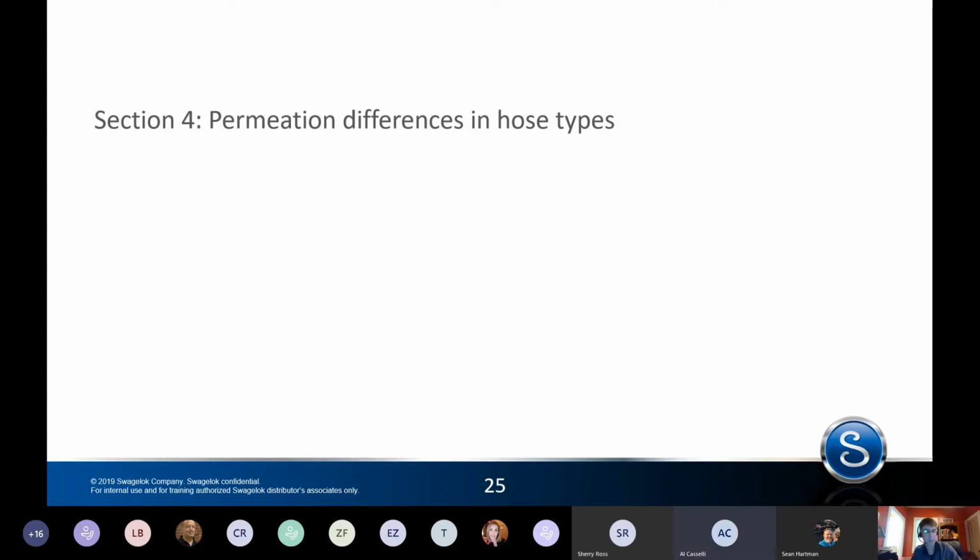Sure thing. With all that being said, what are the medias that you would suggest using the static dissipative hoses with? The most common we see is steam, by far. Probably half of what we see being returned for static dissipative, or lack of static dissipation, I should say, electrical sparks, is because someone used a hose with a steam application that wasn't carbon core.